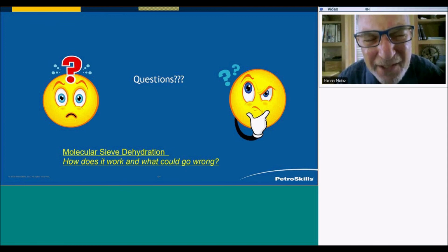I have not seen or done a chilled mirror test on the outlet of a dehydrator. I don't know if a chilled mirror is going to work at less than 1/10 of a part per million by volume. I understand about the response times. I thought Amatec had a fairly robust response time, but I could be wrong.